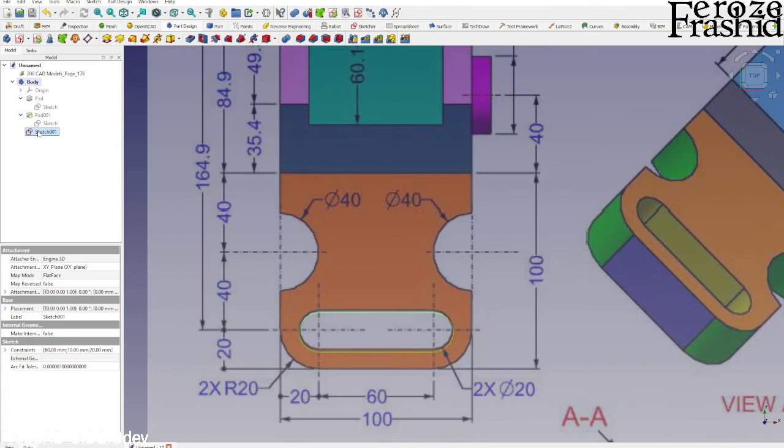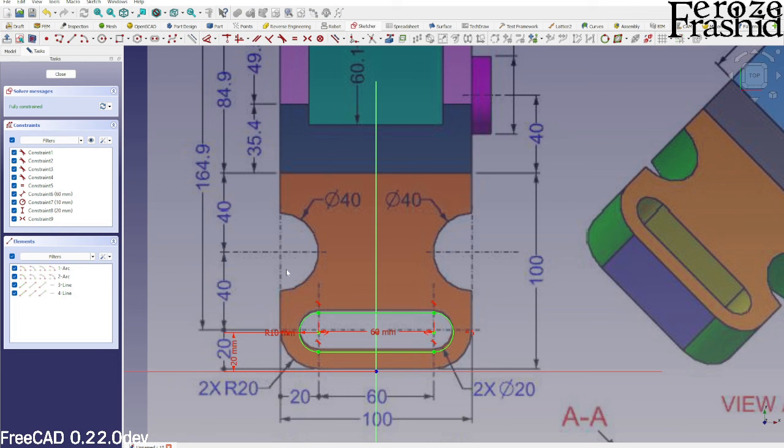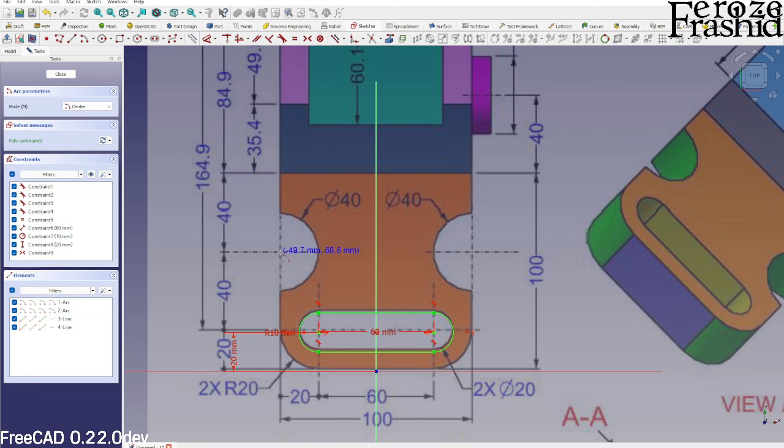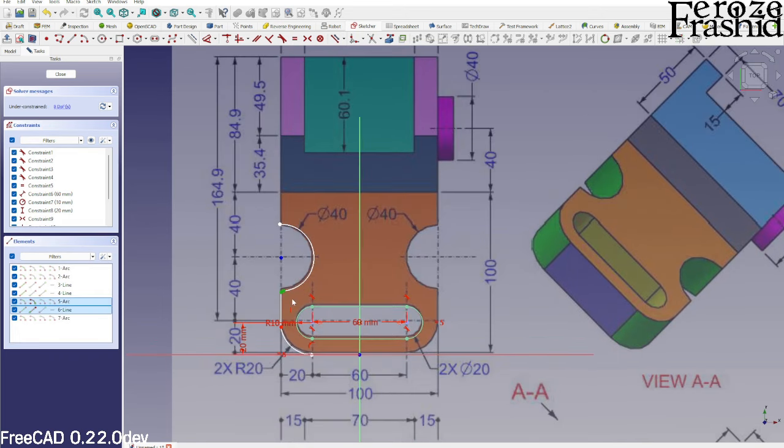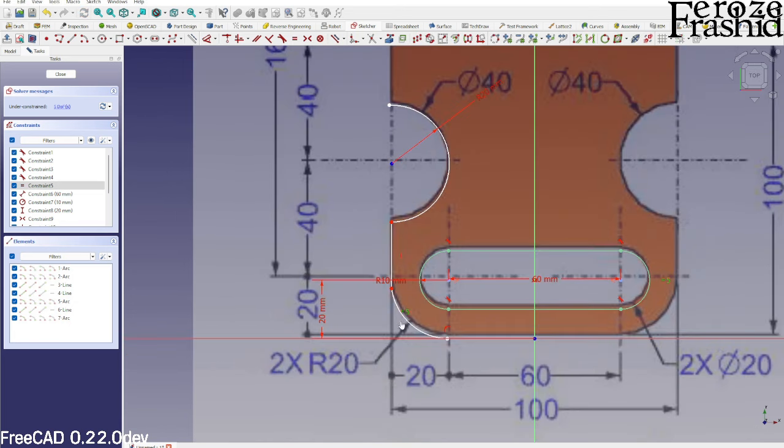All right, so I didn't have to close it. I'll have to do work on this one too. So now I can go draw an arc in here, and then maybe a line. Maybe I should have gone with the polyline. All right, so I got this, and what I'm going to do is take these two, make them coincident, C on the keyboard, and then apply dimension 20, and so these two will be the same.